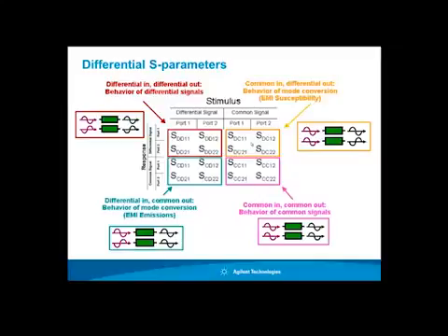That's going to be indicative of crosstalk, either susceptibility or emissions, and so we have to be very careful about doing that. In fact, with something like PLTS software, not only can you measure the magnitude of crosstalk, but you can locate the spatial location of it inside the channel when you use these powerful mixed mode S parameters.